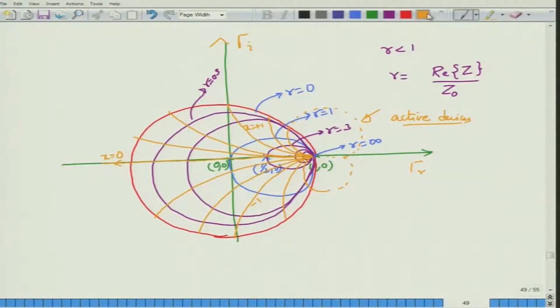So this Smith chart is actually a relationship between the complex gamma and the complex Z values. Let us pick a particular value over here. We will call this the value that I have picked, and I am circling it; I have purposefully exaggerated this circle, but this is the point that I am considering. What does that point represent? Let me also denote the center of this Smith chart as point O, and the point that I have marked here as A. So what does this point A really represent? In the rectangular gamma chart, it represents the corresponding values of gamma R, the real part of gamma, and gamma I, the imaginary part of gamma.